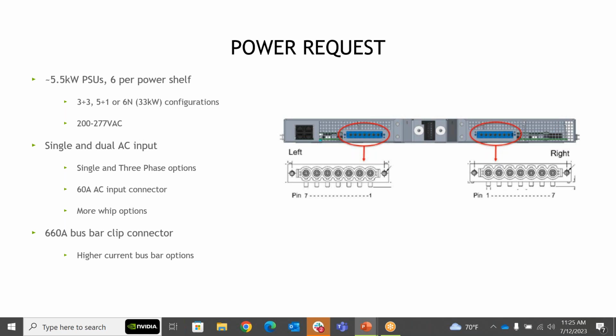Very fast on the 50 volt rail is a couple of amps per microsecond. We certainly do want to talk with the supply base about our methodologies for handling that step load in the AC to DC supply. Contrary to pushing up the density, having more bulk capacitance really helps to smooth things out.